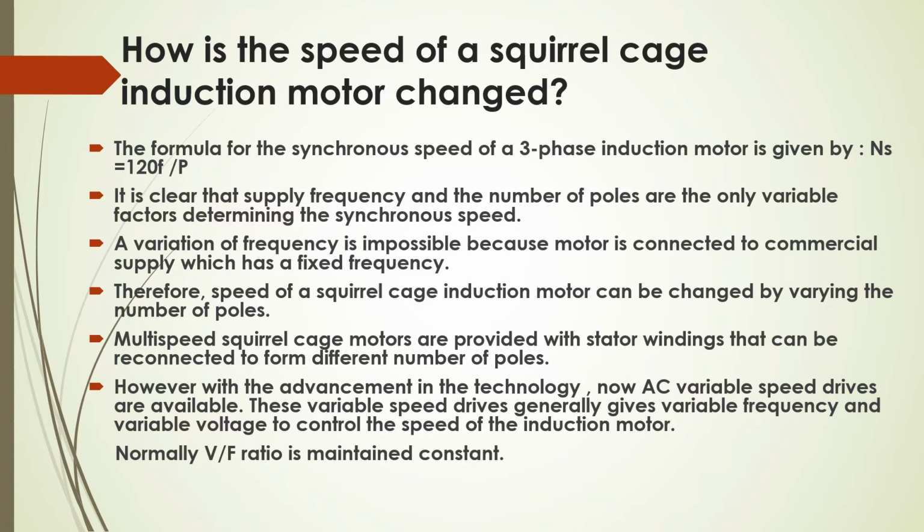However, with the advancement of technology, now AC variable speed drives are available. These variable speed drives generally give variable frequency and variable voltage to control the speed of the induction motor. Normally, the voltage to frequency ratio is maintained constant.